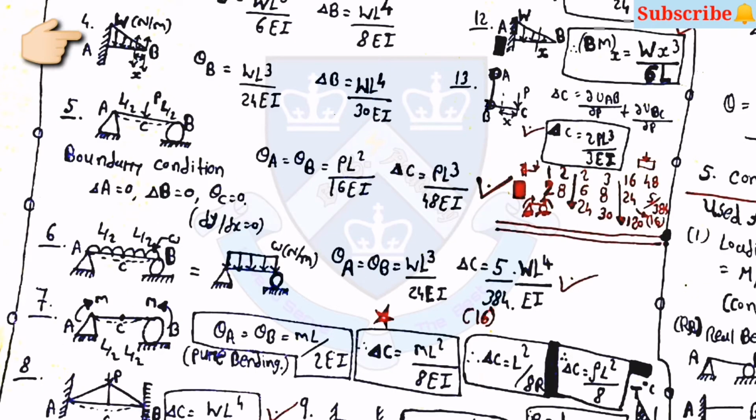Then for UVL, theta B is equal to WL cube upon 24 into EI and delta B is equal to WL raised to 4 upon 30 into EI. Then for the fifth type, the load is acting at the center: theta A is equal to theta B is equal to PL square upon 16 into EI and delta C is equal to PL cube upon 48 EI. Then for the sixth type, theta A is equal to theta B is equal to WL cube upon 24 into EI and delta C is equal to 5 by 384 into WL raised to 4 upon EI.